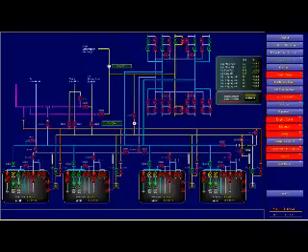So what should be our, as a chief officer or a cargo engineer, what should be my alarming pressure that I start asking the terminal, please, in case... Give them ample time. See the projection. That's why we record the temperature. See the graph on your ship, how the pressures are falling. So you will always understand this is where I'm going to be in the critical position after 20 minutes, after 1 hour. So you tell them earlier.